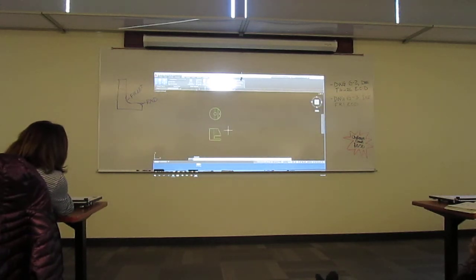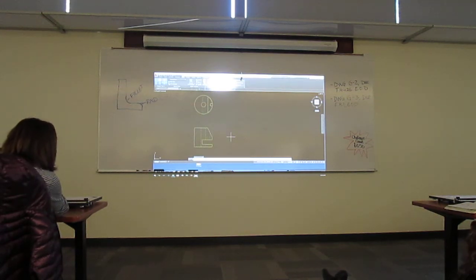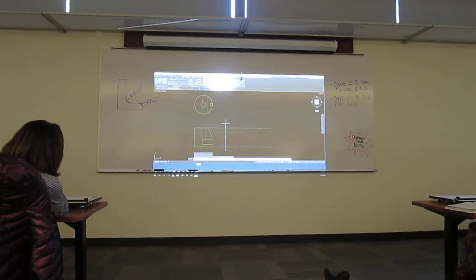All right, so here's your two-view drawing. The first thing we need to do is set up a transfer method. So I'm basically just going to get my miter line going here. I'm going to take the height over. I'll just pick a depth spot right here. Bring that up. Bring this line over to here, and then we'll shoot it at 45 degrees.